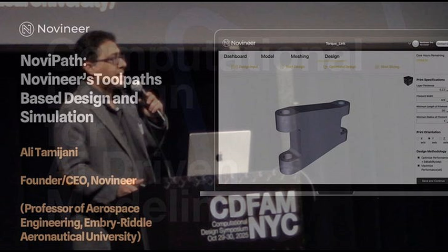If there is no software doing it, then how do users in industry use FDM? These are the two ways they do it. Either they experimentally evaluate it, which takes days, if not weeks: building the fixture, printing, testing. Or, we have heard from several large OEMs during the last 2 years that they consider the weakest property and treat everything as isotropic, which means a factor of safety of 3. That is like designing a dishwasher, not parts for aerospace, right?